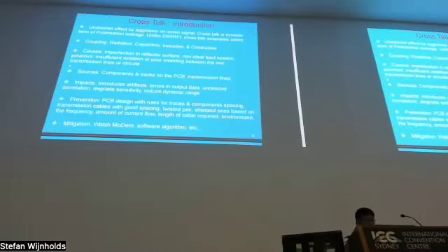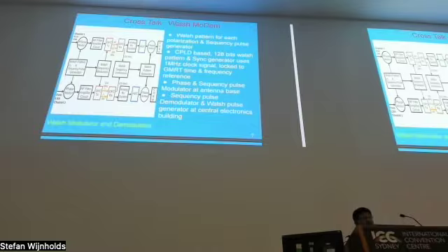If at all it appears in the signal, then we can use Walsh modulation and demodulation methods and some software algorithms to reduce this crosstalk. So in GMRT we have implemented Walsh modulation and demodulation. Here at the antenna base we have implemented a CPLD-based 128-bit Walsh pattern generator, which uses the 1 MHz clock signal locked to the GMRT time and frequency reference.